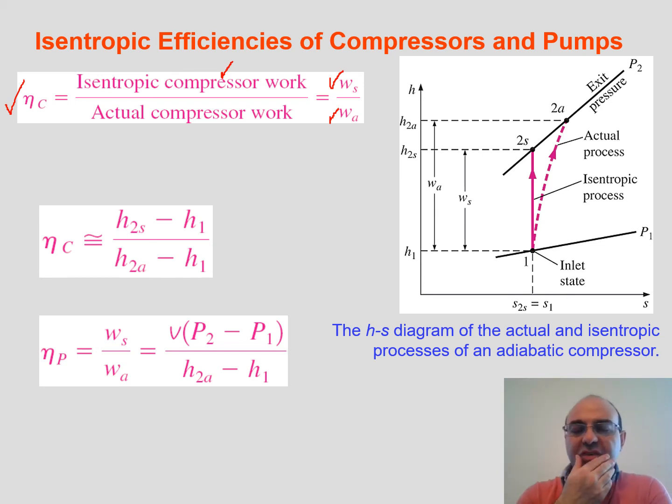But from previous slides, we noticed that an isothermal compressor actually needs less work than an isentropic compressor. So we need to be careful about what we are talking about. We are talking about a device which is adiabatic for sure, and then we say that if it is also reversible, so together adiabatic plus reversible is isentropic, and that's the best device under the condition of being adiabatic.